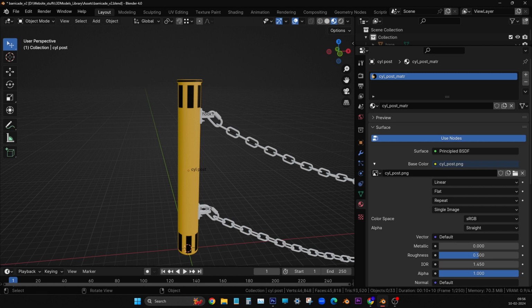So now you go to the layout module. Now, just listen, don't do anything. You want to copy this same material to this object. Instead of going to the data block, that is, we were choosing the data block, instead of that I want you to copy the material from this object, so that you will learn that tool also. So first select the white color box, the one without material.